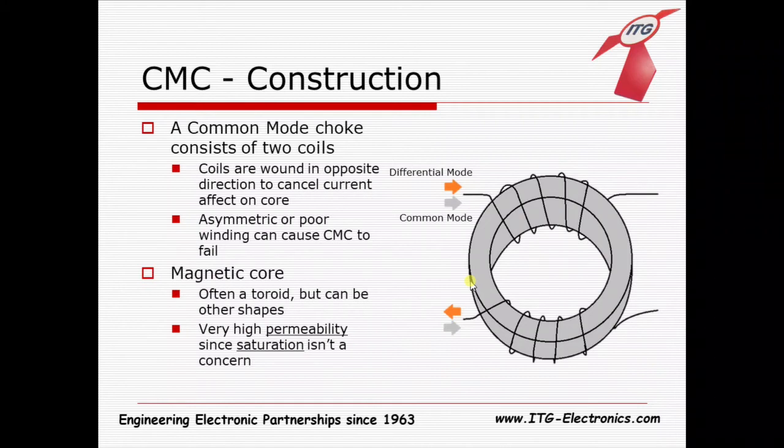So saturation is effectively when current increases going through a choke, it will have an adverse effect on the inductance of that same choke. So as current increases, the inductance drops. And inductance is directly tied to impedance, which is what helps you attenuate a noise signal. So as current's going up, your attenuation and effectiveness to filter out noise is actually dropping. So that's obviously not what we want.